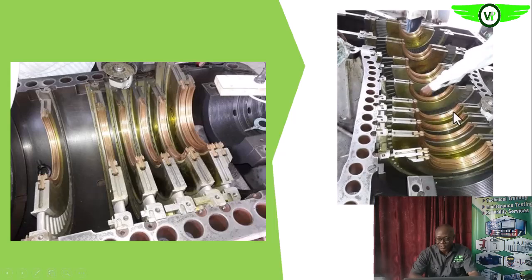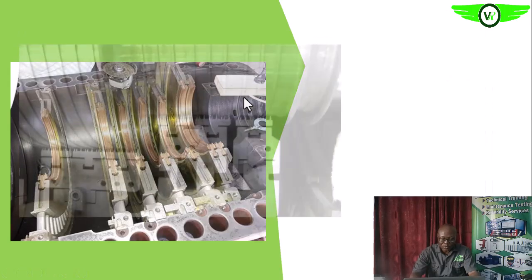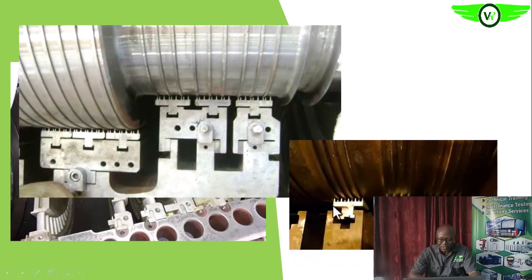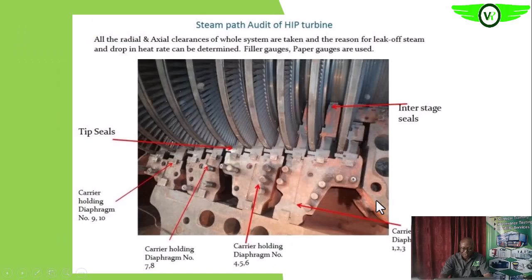So for all of these shaft seals, if the clearances are outside the tolerance limit, then it is time for the seal change out. The clearances must be within tolerance so that the sealing system will be able to work perfectly. The shaft seals, especially the clearances, should be within tolerable limits.